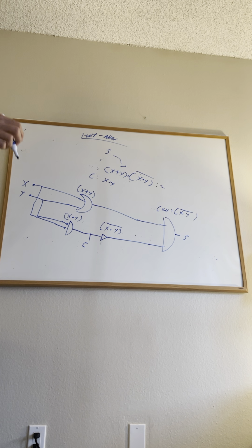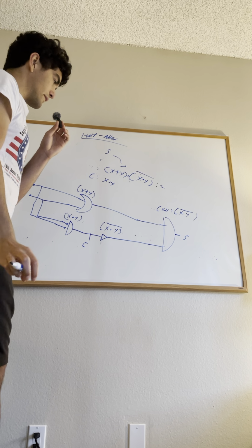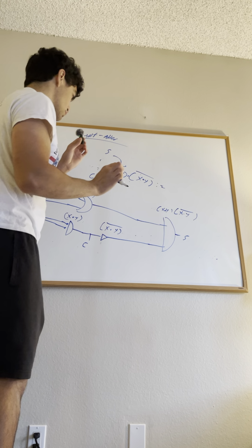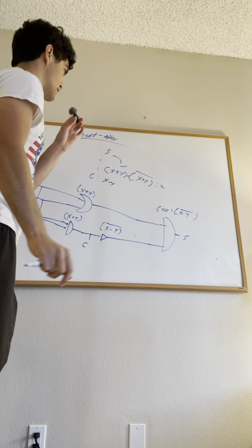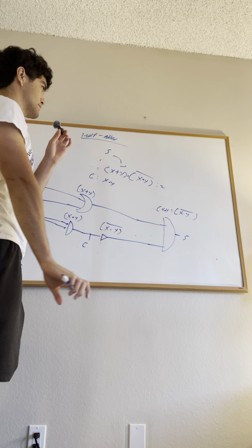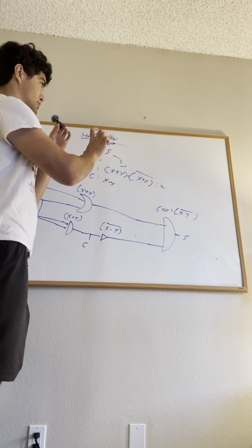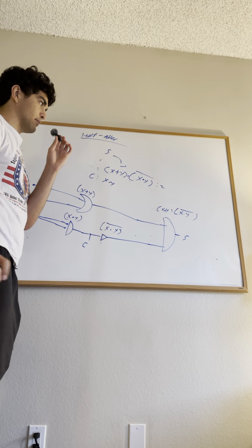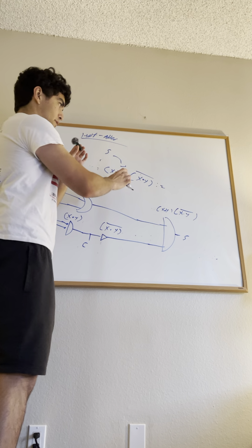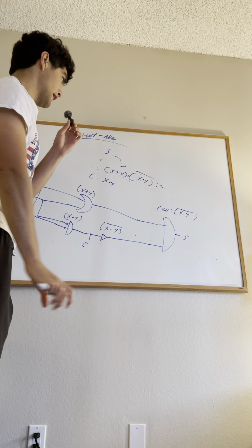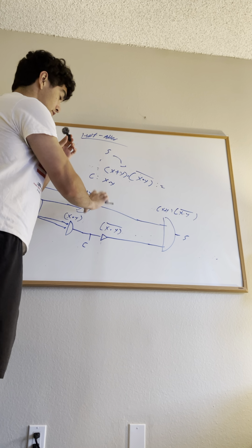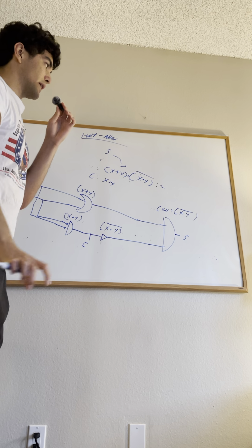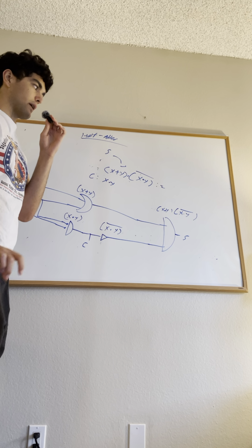And so now, this looks super abstract. Like, what are we even doing? Just to recap what we've done, we've looked at what it looks like to add 2 bits as an abstract table. We've converted them to these Boolean expressions using our sum of product expansion, and then finally we've turned this expansion into logical gates, which we've put together to make a circuit that adds 2 bits together accurately.